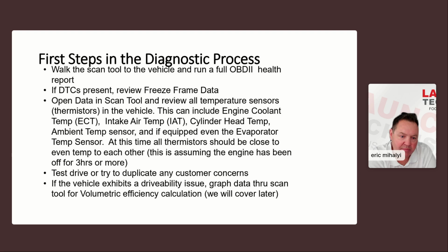Now you may have ambient higher than the intake air temperature, or maybe intake air temperature is higher than ambient because the car is black. It's sitting in the middle of the parking lot with no shade. So underneath the hood of a black car, it's hotter. But you're looking at about a 5, maybe 7% difference at the most, right? If one is off, it can be an indication of what you have. And I have seen so many problems with vehicles. You think about an engine coolant temperature sensor.